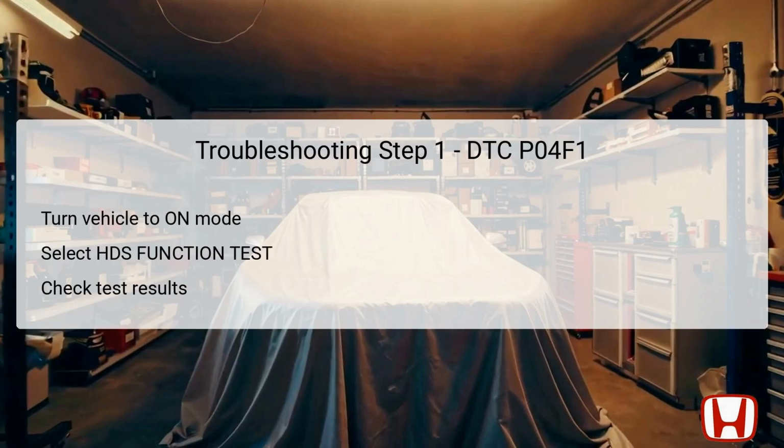The first troubleshooting step in addressing DTC P04F1 involves preparing the vehicle for diagnostic testing. Start by turning the ignition to the on mode. This powers the vehicle's electronic systems without starting the engine, allowing access to diagnostic settings. Next, use the Honda Diagnostic System (HDS) and navigate to the Function Test section. By selecting the appropriate test for the EVAP system, it is possible to determine if the system is functioning as expected or if it is triggering any failure codes. Keep a close eye on the results displayed.